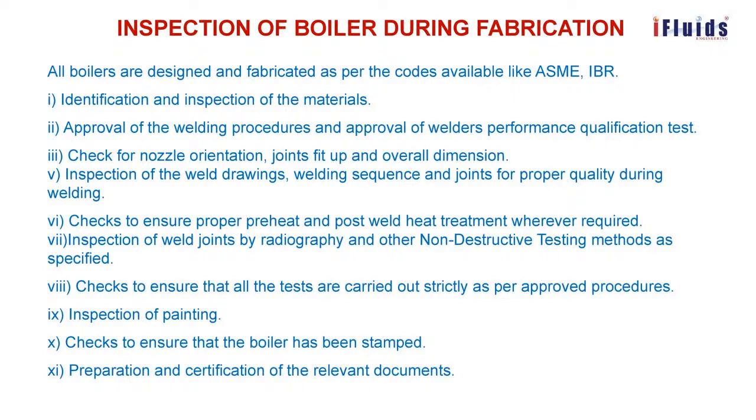During fabrication, the inspection objective is identification and inspection of the materials, approval of the welding procedures and approval of welders' performance qualification test, check for nozzle orientation, joints for fit up and overall dimension. The check for nozzle orientation.